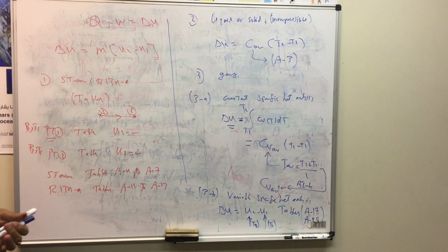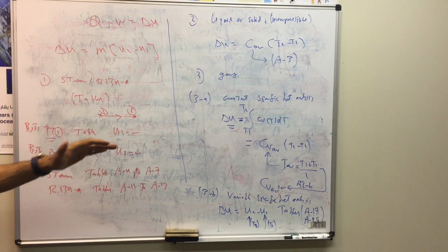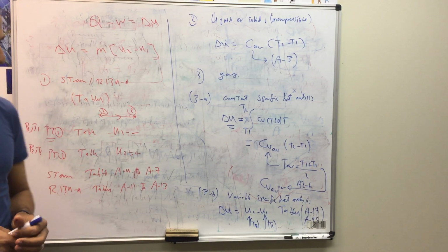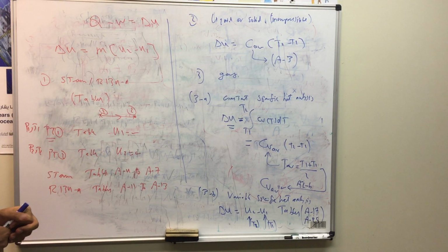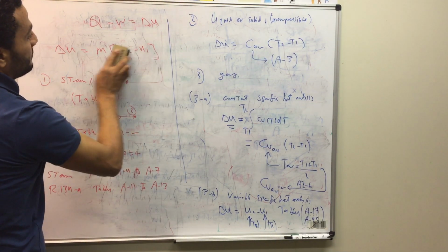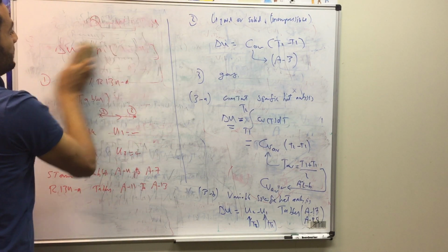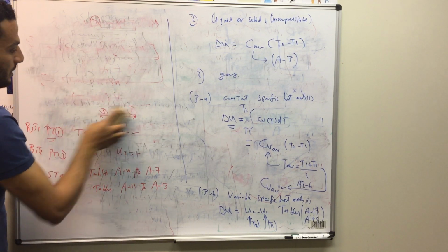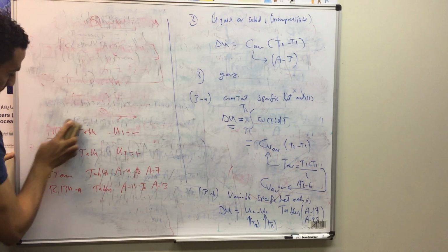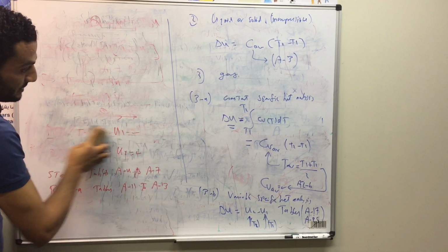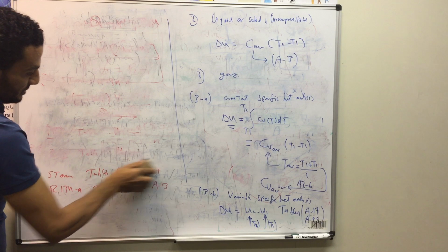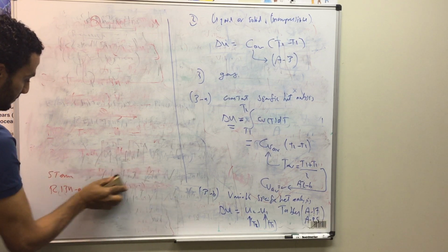Depending on the given substance. And this is actually the second case. There is a third case, which is using the integration to calculate delta U. So in this case, we have to do the integration, get Cv as a function of temperature, and just substitute in this equation, delta U equals the integral of Cv dT, and then we can get the value of delta U.